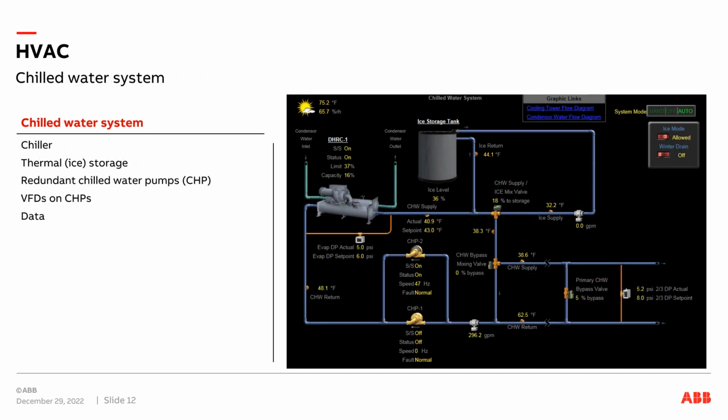Now, everything I've talked about up to this point has been more on the air side. I did reference that some chilled water magically appears at the air handler so we can cool down that air. So now I'm going to talk about where that chilled water magically appears from. I know there's a lot on this page, and we'll walk through and I'll simplify this into some smaller loops. One thing I should mention is that the building I'm in uses a chilled water system. Somebody might call it a chilled water plant, to make that chilled water, which then ultimately gets used to cool down the air.